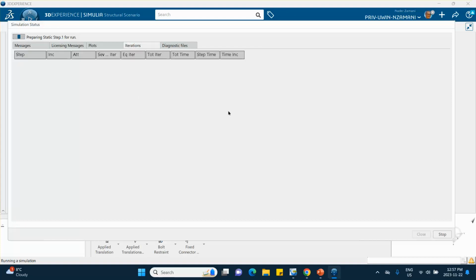Okay, let's check the iteration tab. This will repeat both step one and step two. Of course, step one was already done, but there's no way around it as far as I know, unless you create restart files and things of that type, which we don't want to do. What you see here is step one, which is going to be fairly fast, a repetition of what you already saw. And then once it passes after 1 second, because 1.1, 1.2, etc., that becomes step two.